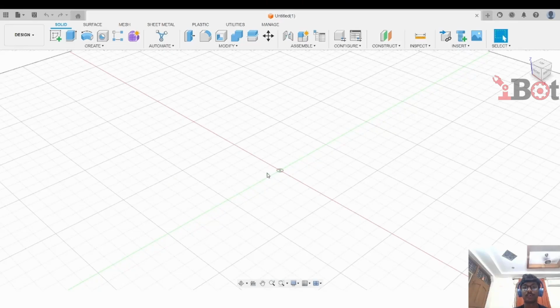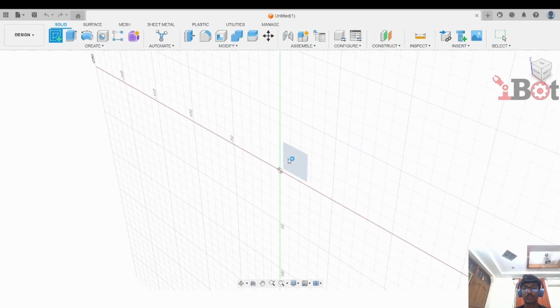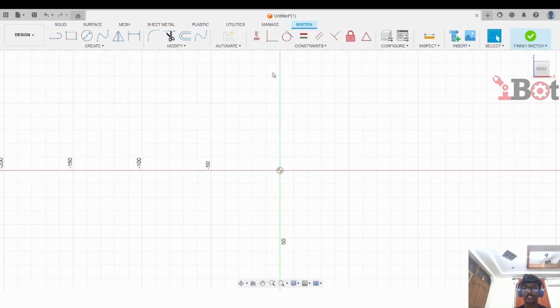Sketches form the backbone of any 3D model. To make a new sketch, select the Create Sketch command and then select the plane where you want to draw. This will lead you to a new sketch tab, which contains three essential drop-down menus which will help you sketch.